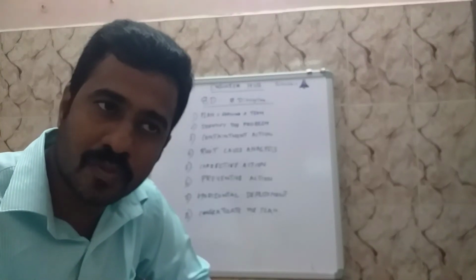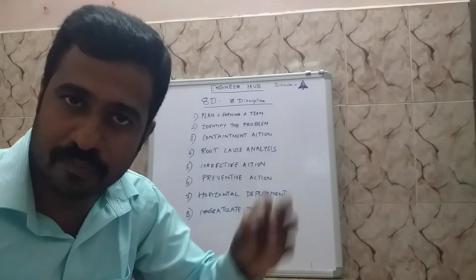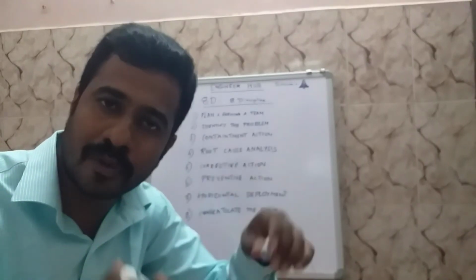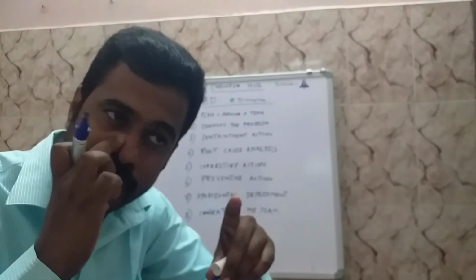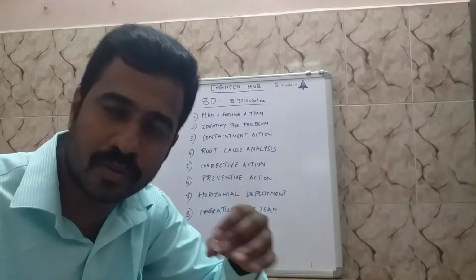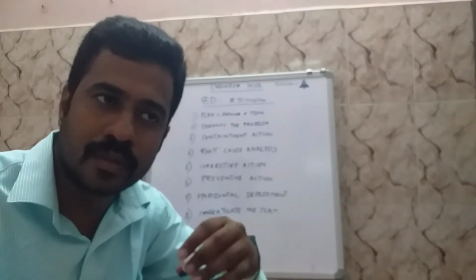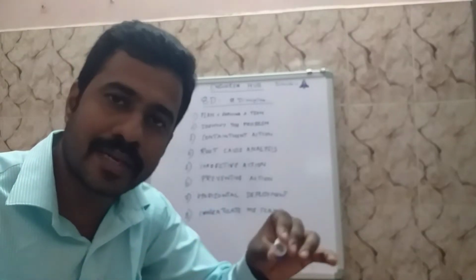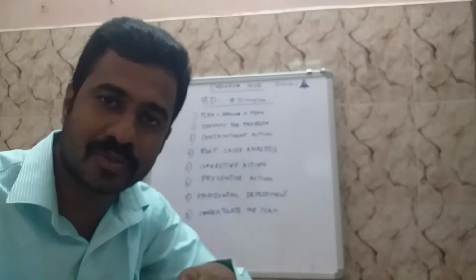You have supplied the product, so what is the condition of the product at the customer's end? And what is the condition at your end, the one which is manufacturing this product? They might have already processed the product and produced almost 1 lakh components or 50,000 components. Those defective components should not come again to the customer side, so they have to scrap them at their end and take some action. That is called the containment action, at both the supplier end and the customer end. That's the third D of the 8D.